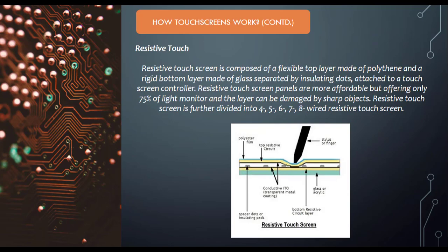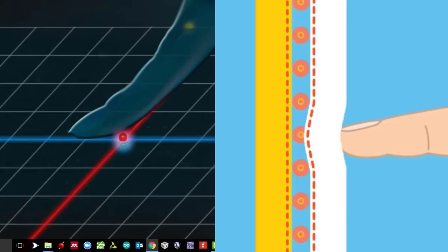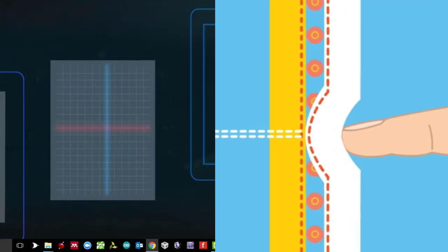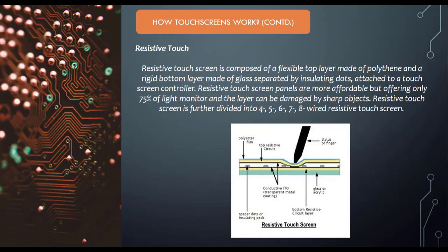When someone presses the touch panel, the top resistive layer bends to make contact with the bottom one, closing a circuit and causing a current loop or a varying signal or voltage. When you press your finger on a resistive screen, the top flexible layer touches the bottom one, and the interruption in the electrical current is noted by the device, which calculates the precise location of the point of contact. Depending on what button is located under your finger, the software registers the coordinates and performs the command.